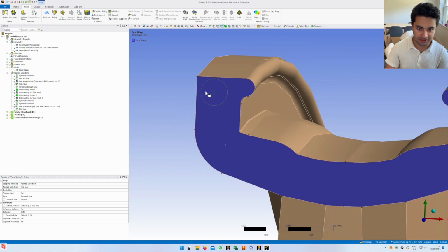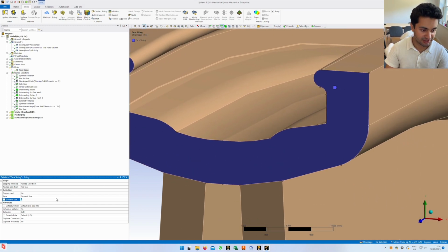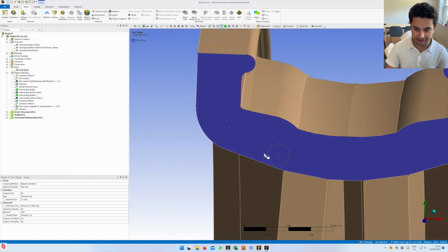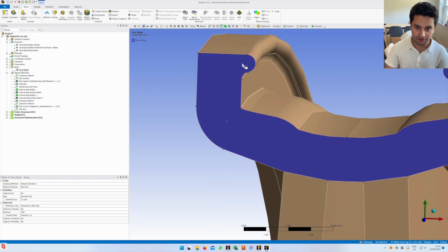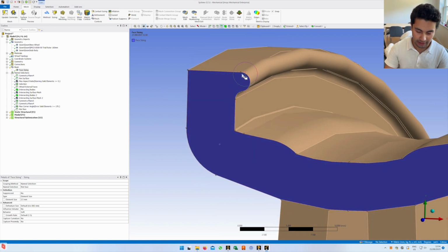And then you'll see, looks fairly good. Yeah, we'll get 2 elements there. Just to be safe, put it down to 2.5 maybe, and yeah, that should definitely be good enough. However, you'll notice we're not really going to capture these details here at the curvature because this element is larger than that actual radius. However, we've got a few options here.